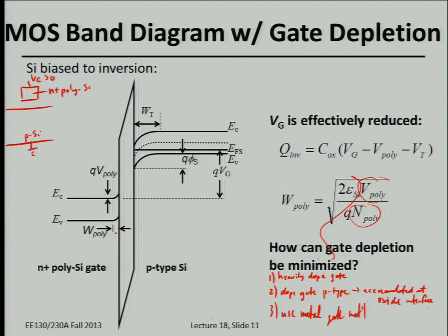You have to keep the dielectric displacement continuous at this gate oxide interface. So you need to have some electric field in the silicon if there's electric field in the oxide. So you do need to have some charge density in the gate. It turns out that you can get that charge by depleting an N-type silicon, or by accumulating holes at the interface.